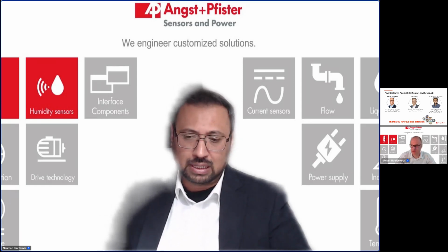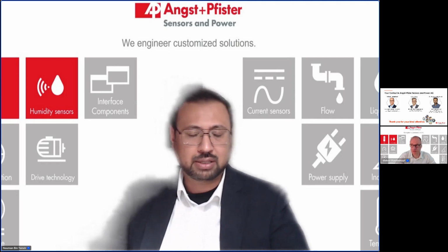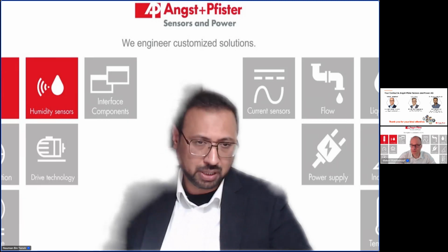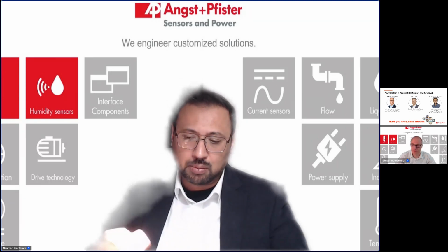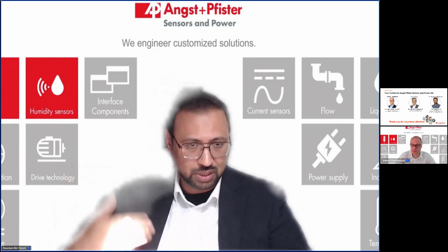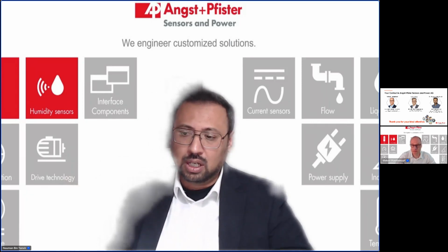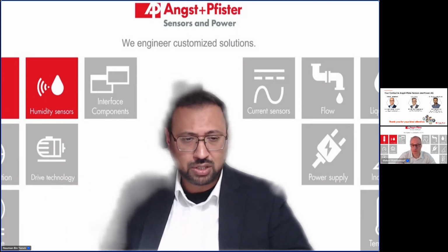Because our sensor can be utilized with two different measurement ranges, we can calibrate the sensor for your application. Let's take the example of 3D printing or additive manufacturing. When the printing process is taking place, you really need to get rid of oxygen content, and this goes really to the ppm level. So you need a sensor that can measure very accurately in the ppm range.